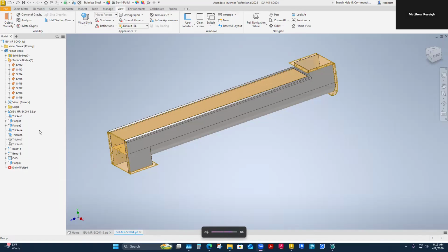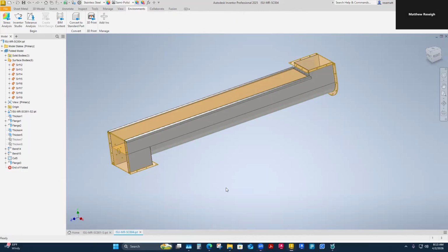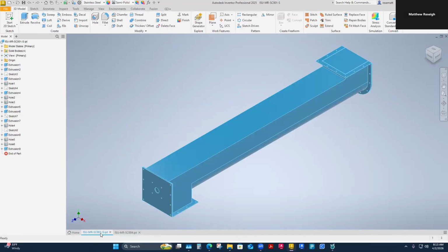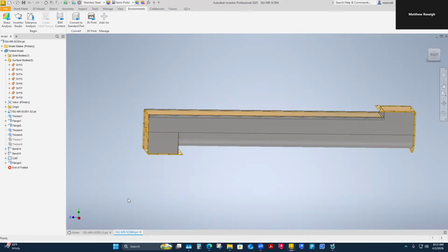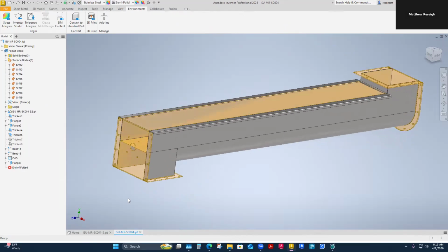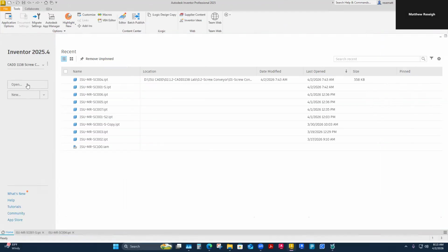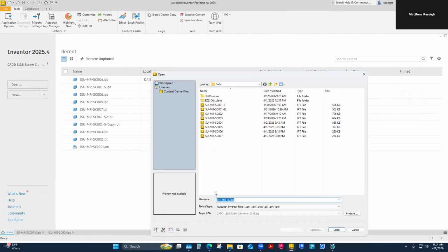What I've got open is just my part assembly. So what we should have at this point is obviously my solid. Then I brought in a part derived in that solid as surfaces. And the other thing I can open here is we exported components, or we made components from that little part assembly that I have there, and it created this assembly.